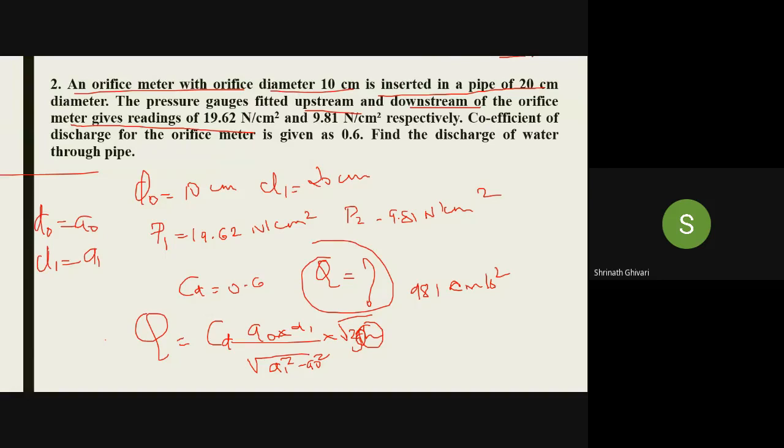So the manometer will be having water. The water is flowing through the pipe. Now, which formula can we take to calculate H? If I go for the previous problem, that is H equal to X into Sg by S0 minus 1. Will it be applicable over here?